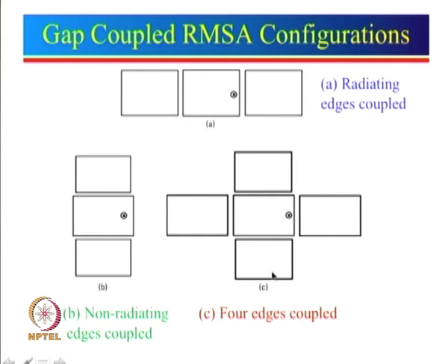So, what that would really result into is that at L1 these patches will be resonant and it will be symmetrical. At a slightly higher frequency, then these patches will be resonant, and since it is still symmetrical, pattern variation will not be there over the bandwidth. And by choosing the 2 lengths different, L1 and L2, we will see that 2 different loops can be obtained in the Smith chart plot.